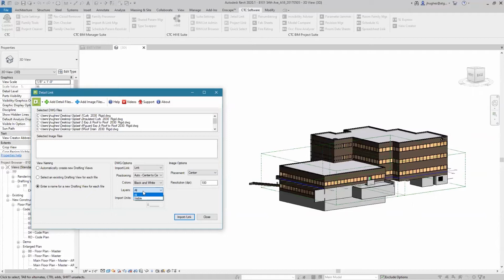But just to make any kind of choices, you got to bring in multiple views. And I normally end up having a bunch of stuff that I put on layers to make them disappear. And then I freeze those layers. And that way I won't accidentally end up printing them. And so I kind of normally say you should probably just trust that somebody's a professional and they chose the correct visible layers that you should see.